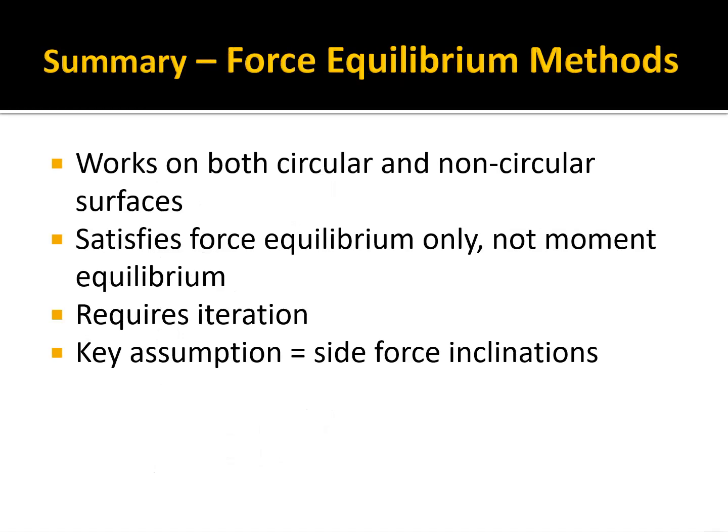So, summary: the force equilibrium methods work on both circular and non-circular surfaces. They satisfy force equilibrium only, not moment equilibrium. It does require some iteration, and our key assumption is what angle those side forces act at.